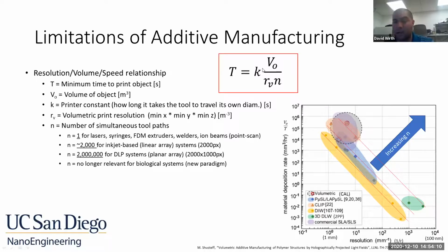And it's going to be accelerated by the speed at which you're moving these deposition heads across your part. You can rearrange this equation into a logarithmic form and plot it on this chart of known printing technologies, and they form these pretty well-defined lines, right? And you're essentially just increasing the size of your machine or decreasing it along these lines.